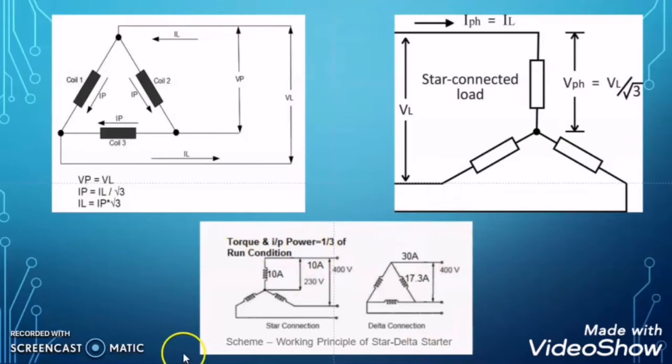Here I have given one simple example. Suppose these are the same motor. In the first case, the motor winding is in the star configuration, and in the second case the same motor winding is in the delta configuration. Suppose this winding has some resistance and is drawing 10 ampere of current. So the line current and the phase current in the star configuration are the same, which is 10 ampere, and the line voltage is 400 volt and the phase voltage is 230 volt, which is 1/root 3 times the line voltage.